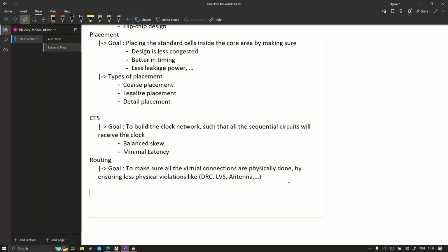So you will get all the signals from a DC perspective only. The fluctuations and everything will be controlled before coming into the chip. Because if we try to insert AC related circuitry into our chip, we need to introduce more modules, which will increase my area, right? So that controlling factor will be outside your chip, or common to your chip.